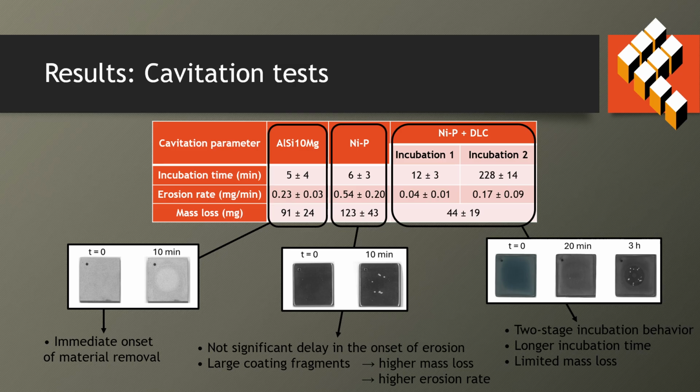For the multilayer sample, a two-stage incubation behavior was detected, where the first incubation period corresponds to the incubation time of the DLC coating, while the second is attributed to the substrate. The multilayer coated sample shows a longer incubation period and then a limited mass loss.